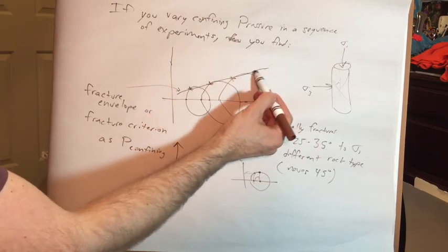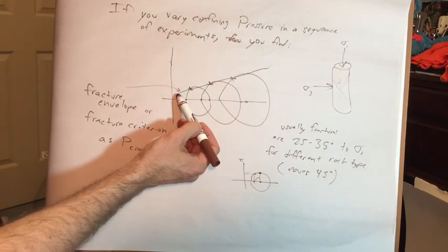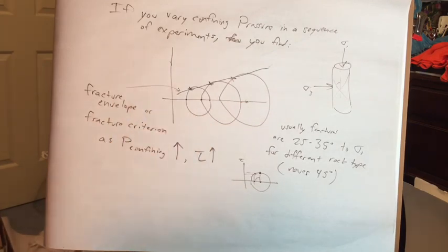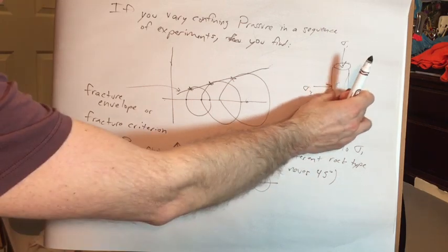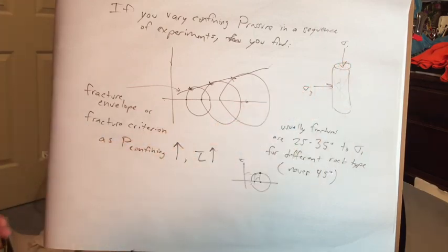And this plot, this surface here, the fracture envelope, gives us a way of predicting when rocks are going to fail. So one of the exercises in the lab on Friday will be to predict the size of a pillar that would be needed in a mine in order to hold up the roof of the mine without having that pillar actually fracture.